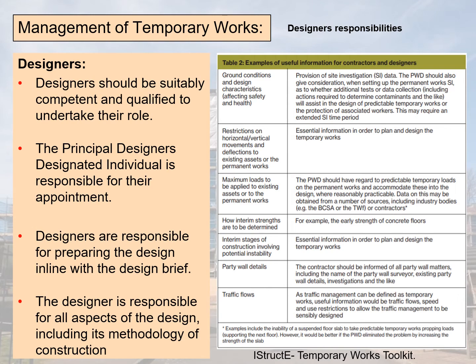Designers of temporary works come under the CDM 2015 regulation requirements. Designers should be qualified and competent to perform their design duties and coordinate design activities. Design organisations should verify the competence of both designers and the checkers for temporary works. Designers should address buildability of permanent works and understand how the temporary works will affect it.